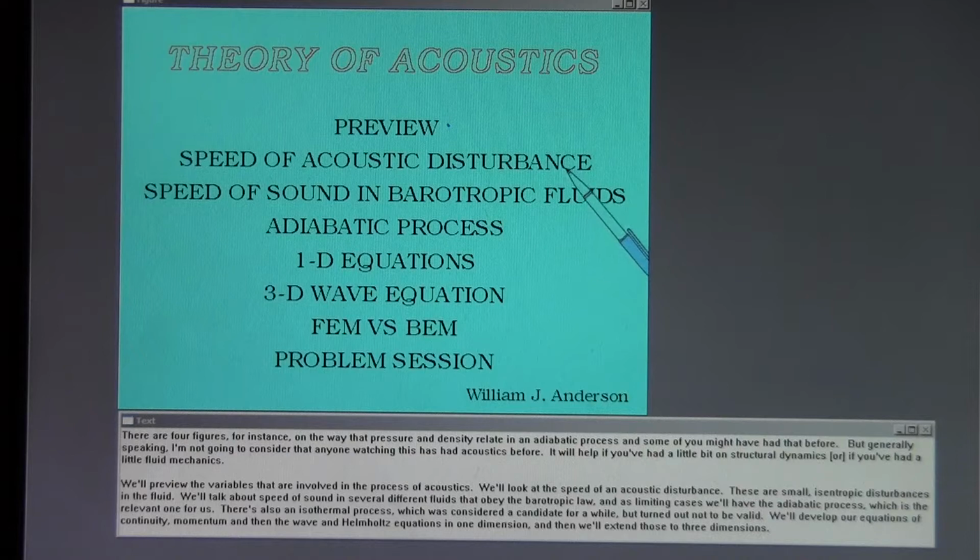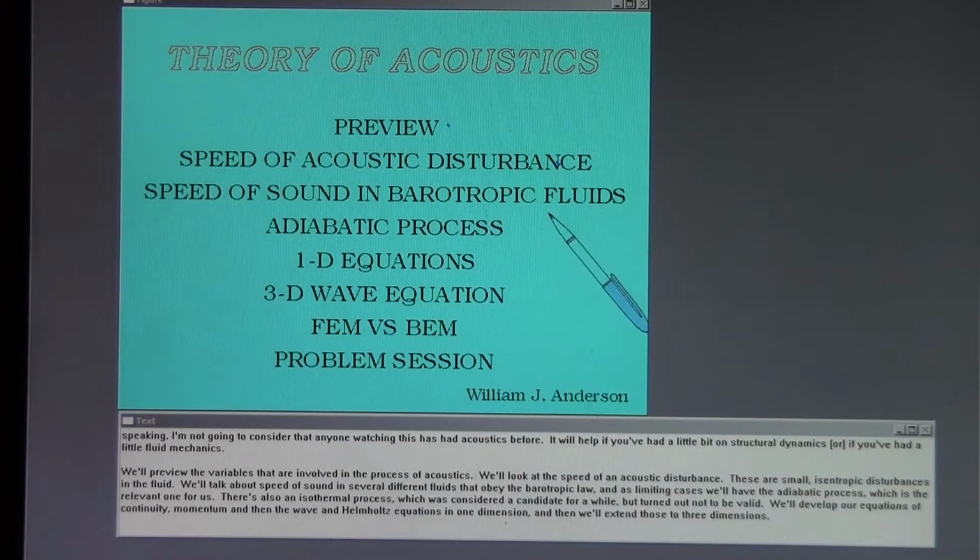These are small isentropic disturbances in a fluid. We'll talk about the speed of sound in several different fluids that obey the barotropic law. And as limiting cases, we'll have the adiabatic process, which is the relevant one for us.